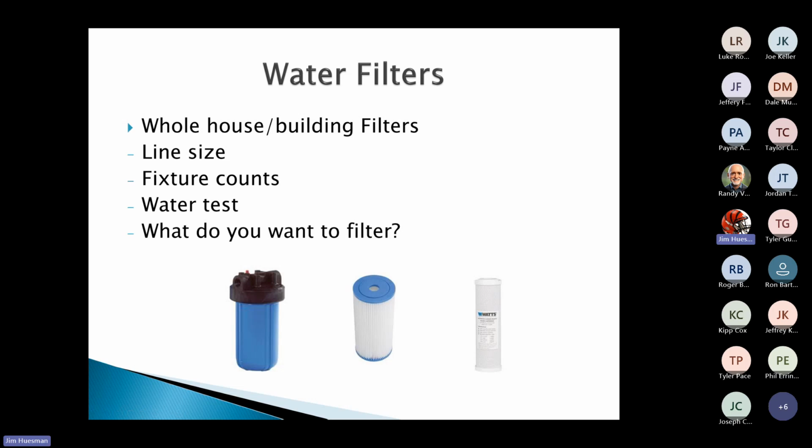So now I'm just going to start off with, I want to filter my water. Now, one thing I'll tell you is please don't look at this as just an off the shelf purchase. There are a couple things we need when we're choosing the filters. One, I'd really like to have those test results. Now I know what filter I'm going to be going after. But I really like to know my line size. What am I working with?